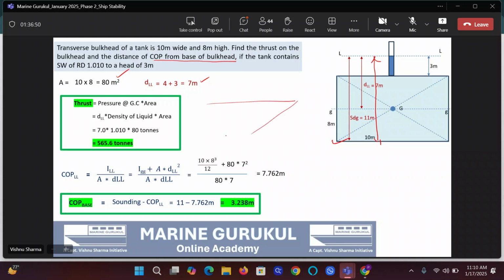Okay, sir. In a ship, the tank in a 3D diagram is like this. The sounding pipe and air pipes are not part of the bulkhead. They are like this. Correct? Are they part of the bulkhead? No. It is confusing you because it's a 2D diagram, right? In 3D, if you have ever been in a tank, the sounding pipe is free of the bulkhead. It's not part of the bulkhead, correct? Okay. Continue. Do the next one.